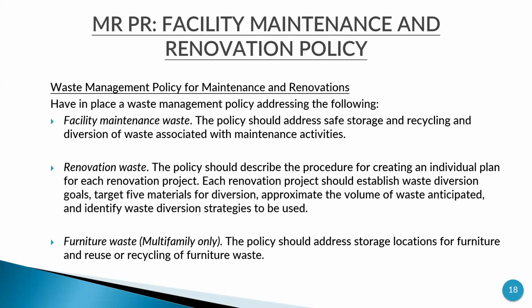Storage and recycling. Then coming to renovation waste, the policy should address the procedure for creating an individual plan for each renovation project. And each renovation project should establish waste diversion goals, target 5 materials for diversion, approximate the volume of the waste anticipated, and identify waste diversion strategies that need to be used.